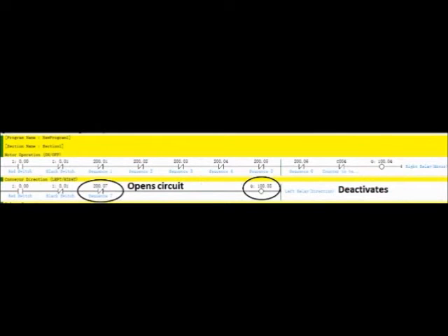At the same time sequence 4 is activated, a sequence for changing the direction of the conveyor belt is activated. This sequence is called sequence 7. When sequence 7 activates, it opens the circuit for the left relay, which enables the conveyor belt to move from left to right. With this relay deactivated, the right relay will then be dominant and the conveyor belt will move from right to left.